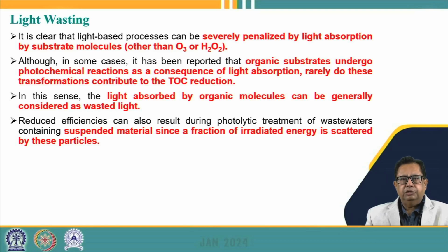So it is necessary to note that when we are having wastewater or water which contains organic compounds, if they are absorbing the light, the light basically becomes wasted, as we are having lesser degradation of the organic compounds in comparison to when the light is absorbed by ozone and H2O2, which results in a higher generation of dot OH radicals, and which in turn results in higher degradation of that organic compound. And similarly, if suspended solids are present in the water, they may also lead to wasting of the light, in the sense that the suspended materials can scatter the light, and it may not reach the ozone or H2O2 present in the water or wastewater, and it may result in lesser efficiency of the degradation.